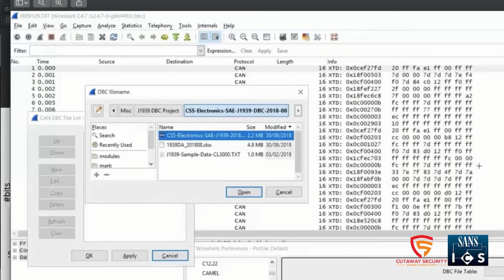And then we can scooch our way in until we get to the one message that is the unlock the car message. And you can probably imagine that can be useful for cybersecurity, but it's also a good, easy way of narrowing in on something that you're trying to figure out when you don't have a whole bunch of insider information. And I think that was one of the recommendations, like the hello world for CANbus when dealing with cars.